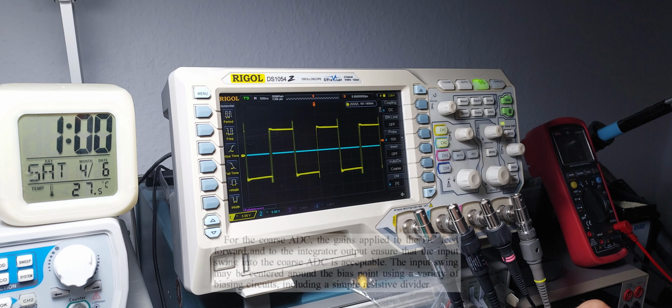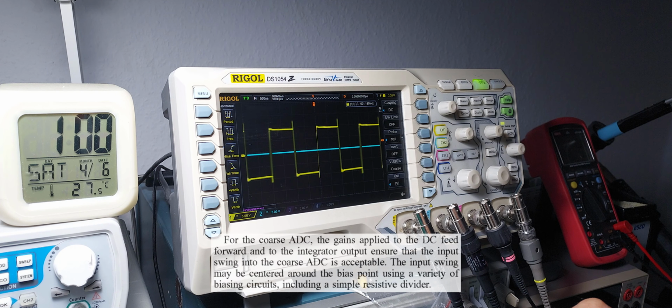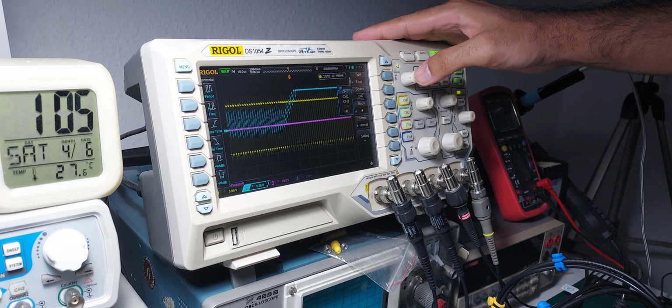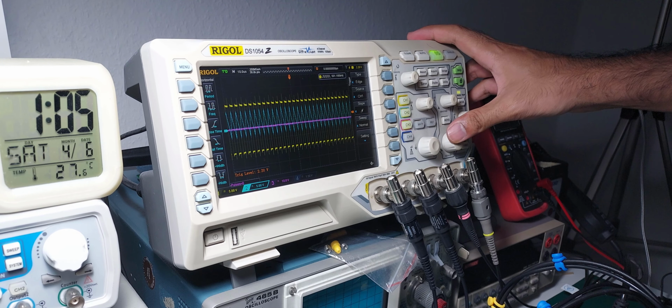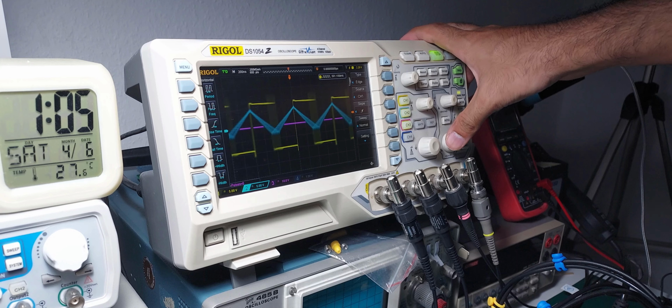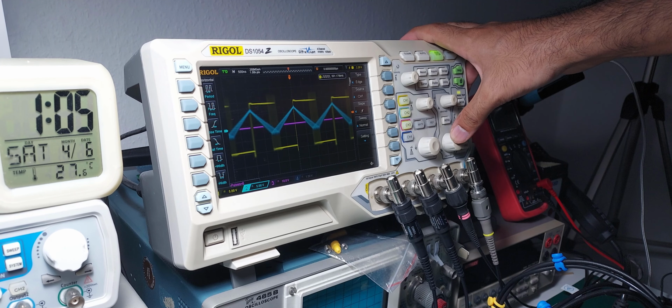This could be to center the waveform around the coarse and fine ADC's inputs, like the patent says. Ramping through the entire input voltage range, we observe that the integrator peak to peak swing is tightly bounded, which is something I didn't see in the primitive simulation. Maybe the PWM frequency changes slightly to keep the integrator within a certain limit, although I'm not sure what advantage